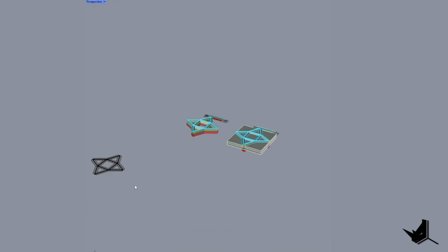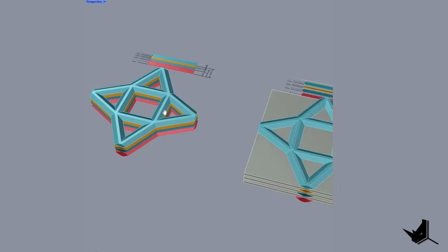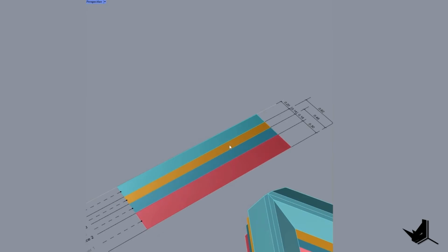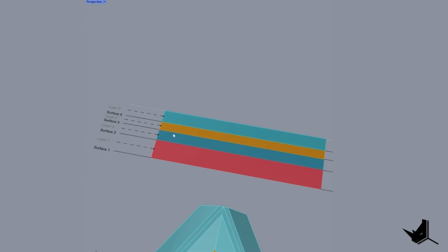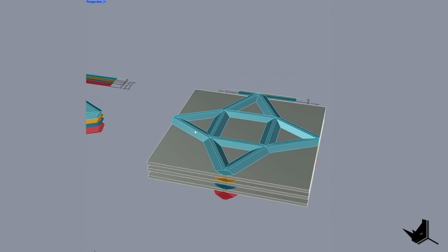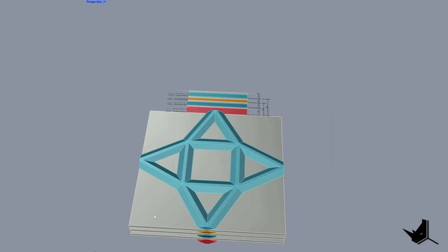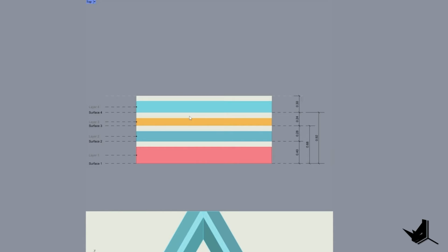As our surface is smooth, and that smooth surface will apply a rectangular, or actually square, grid, we'll get a jagged surface, and we might get some intersections of the models between the layers. That's why we need to create gaps between the layers. I define the gap in my case as 0.1, but you can set another value if you want, and we get something like this.